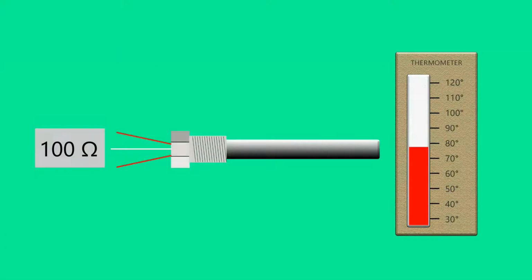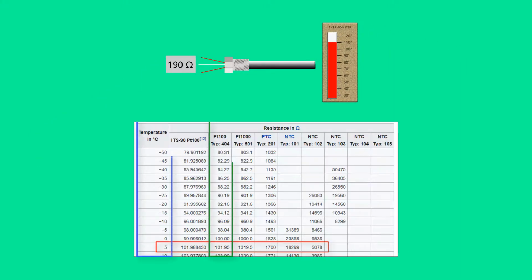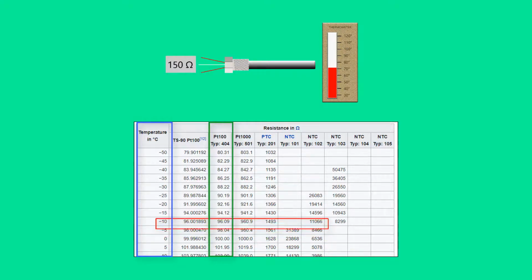A resistance thermal device, RTD, changes its resistance with temperature. The standard RTD value creates 100 ohms of resistance at 0 degrees Celsius. As temperature increases or decreases, the resistance of the RTD changes. RTDs produce a linear resistance with temperature changes and, as a result, a linear voltage change in the bridge circuit. There are various types of RTDs. Specifications should be used to design RTD circuits.